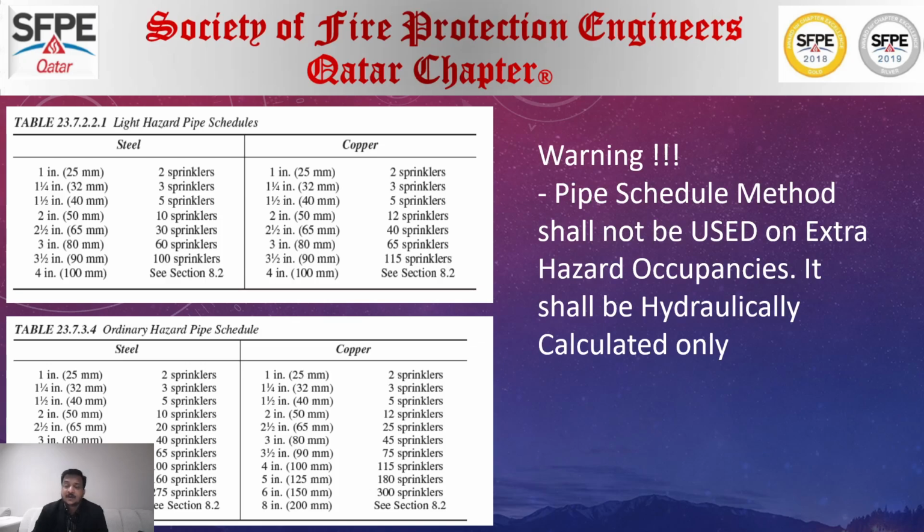And for the pressure, you have to estimate the static pressure required for the building, as well as the friction loss, and the minimum residual pressure which is mentioned in the table. That will be your pump head. So you do not need to look into the area of sprinkler operation, how much area you are going to protect. It is a straightforward exercise.